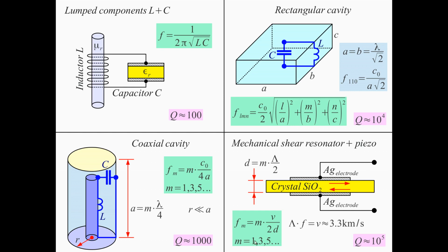We only have odd number overtones here, because even number overtones do exist in the quartz crystal, but they have no piezoelectric coupling. So that's the reason why we are not considering even mode crystals. We will have a separate lecture, since piezoelectric resonators are very important. In fact, silicon is not only useful for transistors.